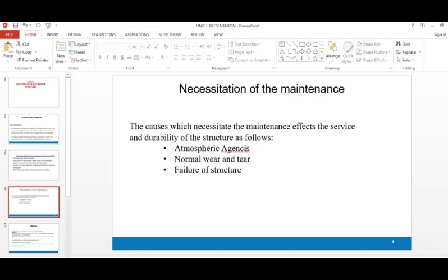So it involves how we can do the remedial maintenance. First we need to find the deterioration, how the damages and where the damages have occurred. Then determining the causes, so how does it occur? We need to determine the causes, and then evaluate the strength of the existing structures and the need of the structures, and then finally selecting and implementing the repair procedure.